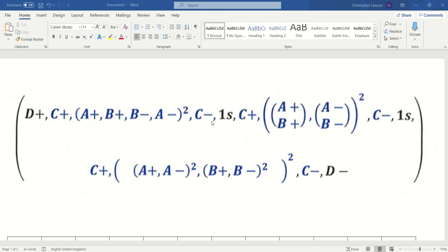next step. Okay, so you've got a time delay in here as well. We also have just 2 cylinders moving in and out at the same time. So in this part of the sequence, you'll see A plus and B plus will move forward together, then they'll move back together, and then we'll repeat it twice. This will move forward together, then move back together. Okay, so that's what the sequence means. So as I said, it's quite long. That's what some of the symbols mean.